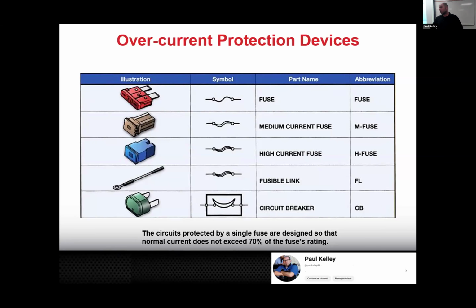Yeah, so sometimes you have to replace the whole cable. Other times you can actually cut it and splice something in, but you don't just get to yank it out and put a new thing in with pliers. So that's part of the reason I'd say fusible links are kind of dumb. I don't like them. It's a cheap way to do it. I'd rather run it up into the fuse box and use like a maxi fuse or something.